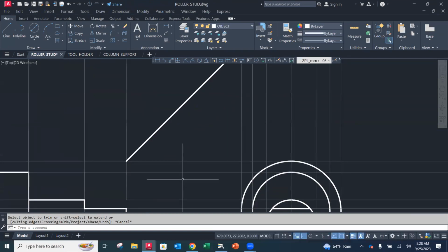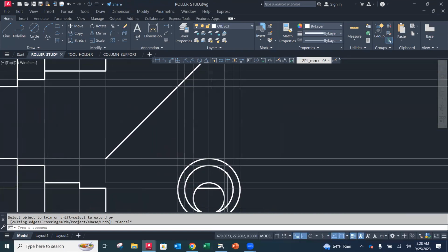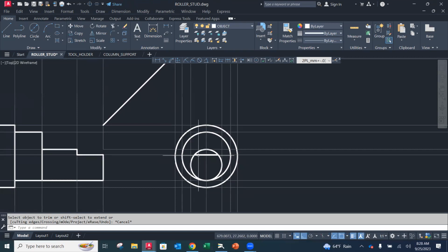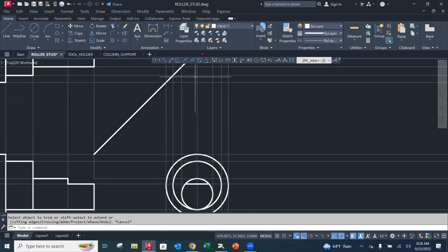Now, you'll notice that when this cuts in the front view across, we have to translate those 2 points up because it doesn't cut it completely across. So we have some extra lines here. I'm going to go back to my construction line layer, to my construction line here. And I'm going to go from the intersection where the cut occurs, where we did that offset of 5. Okay, let me do this again. Intersection, there we go. And intersection.